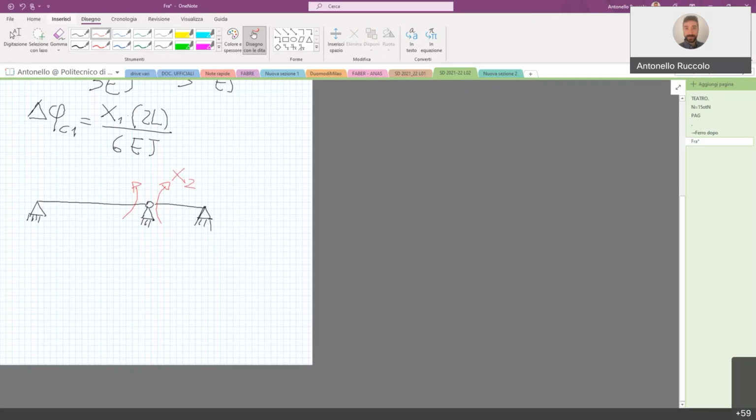If I'm not wrong, this was the direction. The deformation associated is on the beam AC, we have a moment which is counterclockwise. So we will induce a rotation that is counterclockwise in the node C and clockwise in the node A.